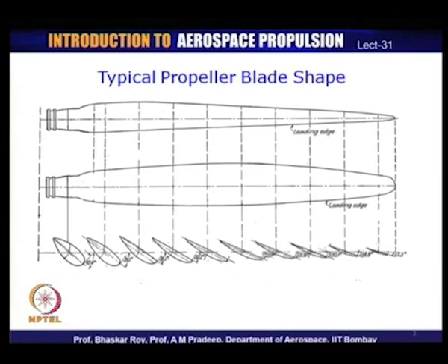But over the years, they used aluminum alloys, cast aluminum, for giving the shape, and later, in the modern propeller era, they are using composite material to give more complicated propeller shapes in the most accurate manner. The more accurate the blade shaping is in conformity with these aerofoil shapes, the more the propeller efficiency is likely to be achieved during actual operation. So, this was a conventional propeller shape.